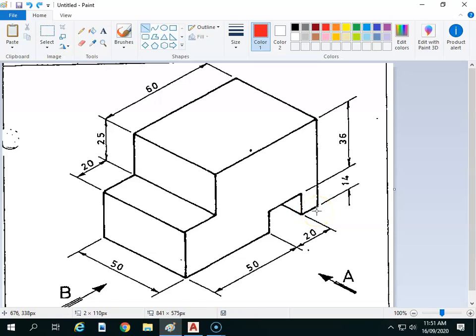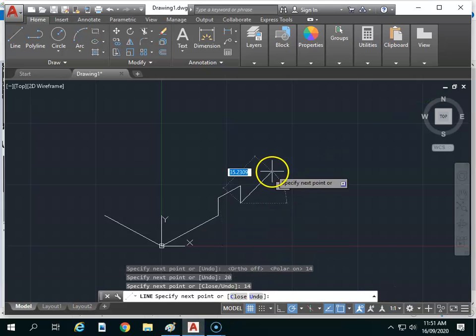And that's generally good practice, right? The idea is you don't want to specify more dimensions than you have to, right? If you specify more dimensions than you have to, well, there's two schools of thought. One school of thought is that if you do specify the dimensions, the first thing you should do is check that both sets line up. In this case, what they want to see is if you can work out the dimension. So they've set up here it's 60 plus 20. So if we've got 50 plus 20, what's the difference going to be here? 10. That's exactly right.